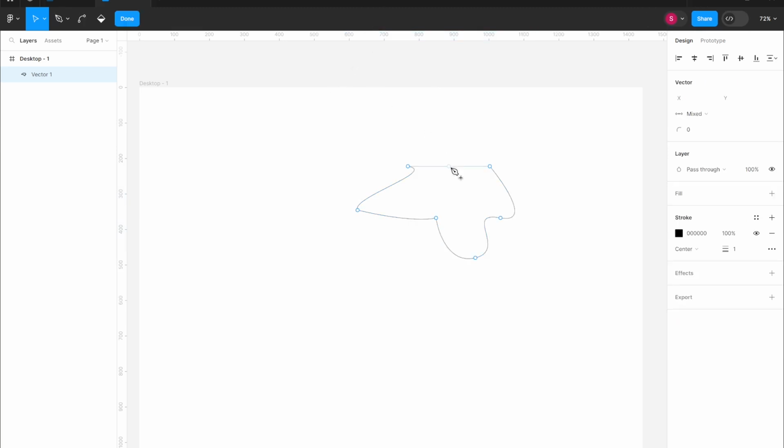After that, we can select and move the points as we want. If we take a point and move it, we do not change its handles, while if we take its handles, we can change them with three different options found here. Mirroring angle and length means that they will shorten or lengthen together and be mirrored at the same angle, and therefore the previous and following segments that the first and the second control respectively will also do the same.